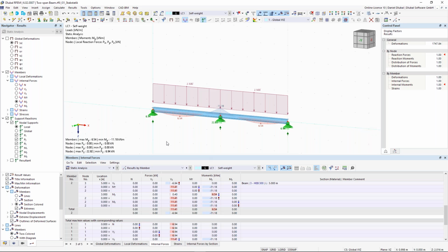So when you work with table books where you can get some results and just put in your dimensions there, then you get some results for the maximum bending moment or shear forces and so on. It's important to know that these kinds of table books don't consider the shear stiffness, and RFEM considers the shear stiffness.